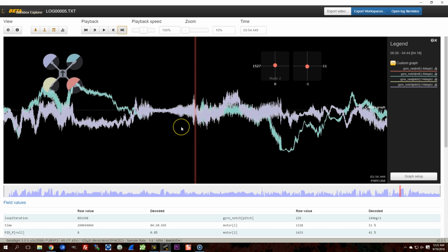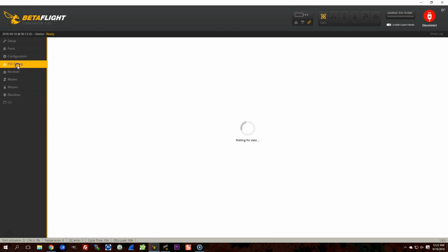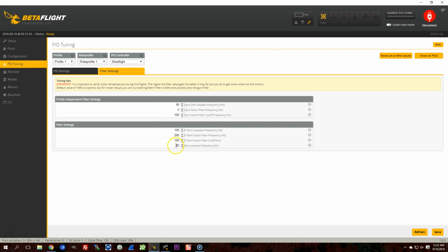And what you'll probably end up finding, if Boris has done his job, is that most of the time your noise is around these values. Okay, so you may find that these values by themselves work pretty well for you, and that doesn't actually require much tuning. Betaflight defaults fly really, really well for the vast majority of people, especially if you're flying a 5-inch mini quad 4S, which is what a lot of people who are doing the tuning are tuning on.